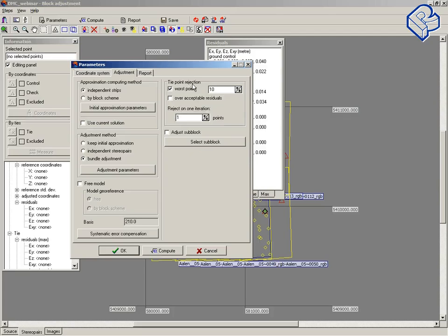But in fact, I do not recommend using it, because it's better to adjust the block, estimate the results, select some bad points manually or by some criterion, and delete them from the adjustment. But I still do not understand completely why it always excludes one point. Probably it's better to send an email to the Rakurs support address.